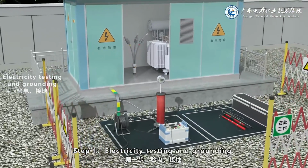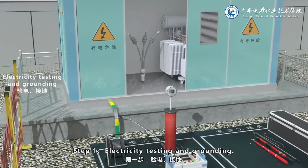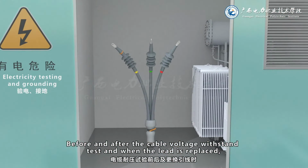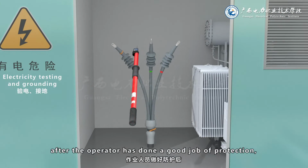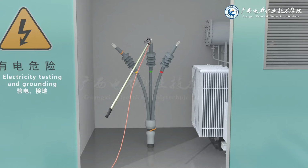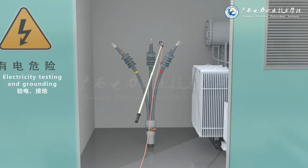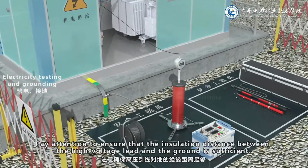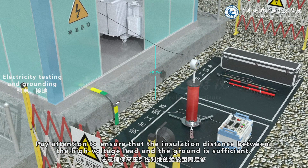Step 1. Electricity testing and grounding. Before and after the cable voltage withstand test and when the lead is replaced, after the operator has done a good job of protection, first of all, the tested products are electricity tested and fully discharged after grounding. Pay attention to ensure that the insulation distance between the high voltage lead and the ground is sufficient.